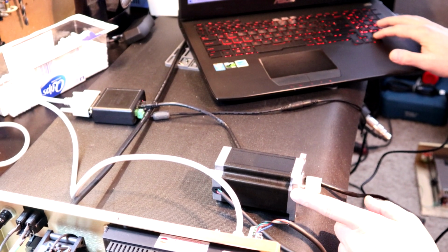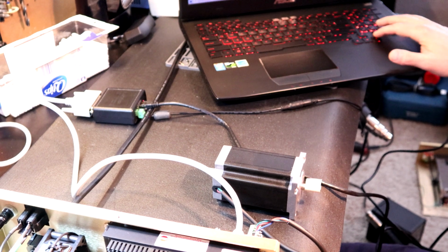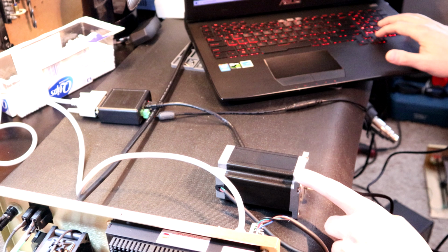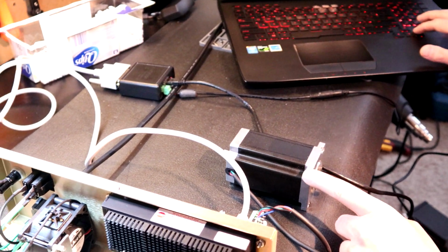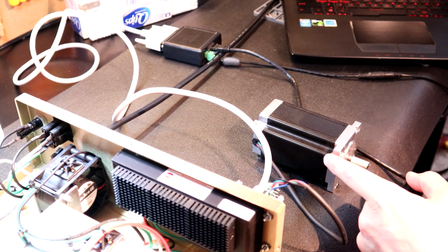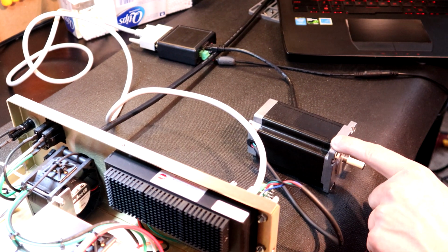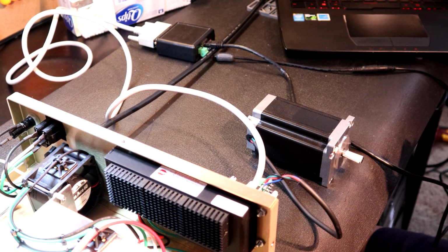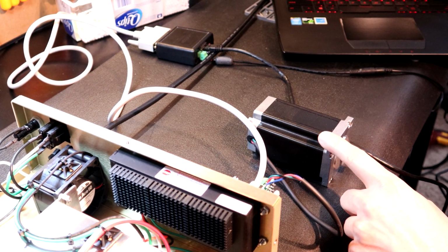Watch how the motor reacts when I go to jog it. You see how it's shaking? Watch. Look at that initial shake. That's G-force. That's all that torque, no different than if you stomped on the gas in your vehicle when you go to peel out. That's what's happening. And that excess energy is being dissipated in your chassis. There is nowhere for it to go. So that's why we always want to have a smooth increase in speed.